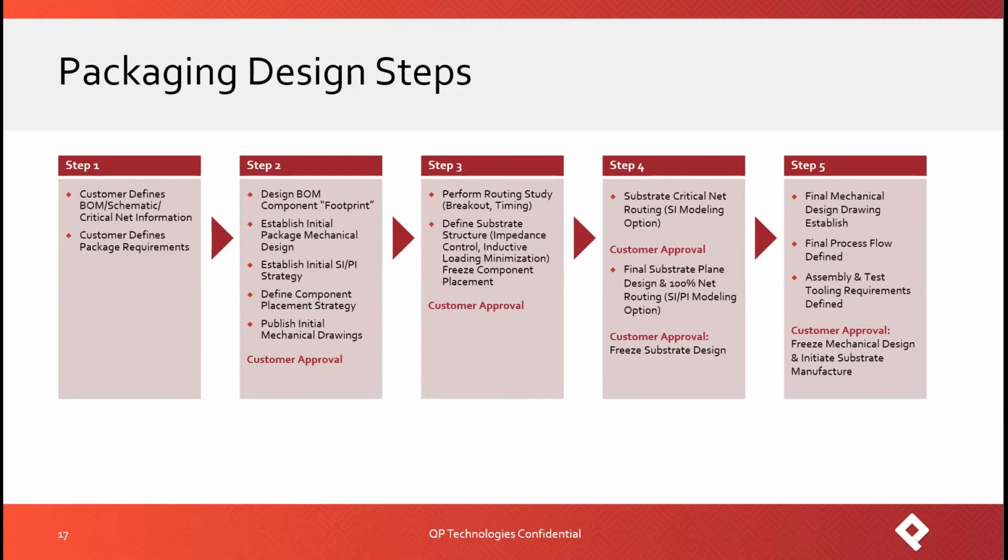Then it goes into even more detail as far as electrical performance requirements, if such were critical. And from there, some modeling. Generally, we find that it's very rare that we're working on a design that requires modeling. Sometimes thermal, but not so often. And sometimes at least some electrical simulation, but not in detail. And the output then is basically released to the Gerbers, to the substrate manufacturer. We do not do substrate manufacture internally. We have a number of strategic partners that we work with for that.